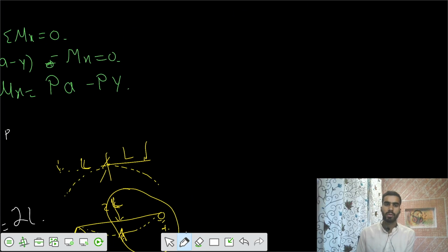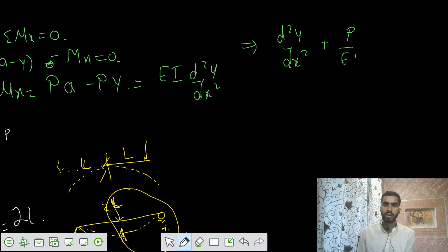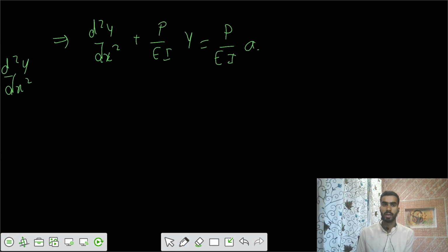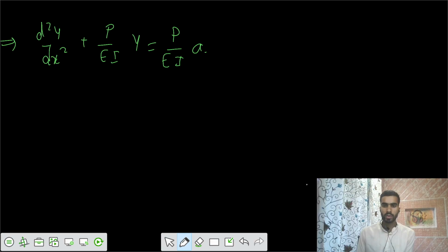So if I use that equation, EI d2y by dx2, similarly I would say d2y by dx2 plus P by EI of y equals P by EI of a. So if I have that equation, your general solution of that equation would become